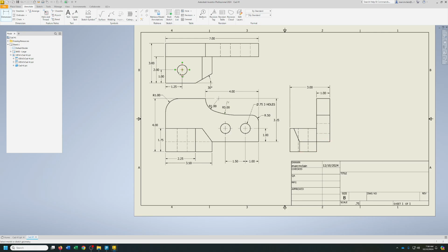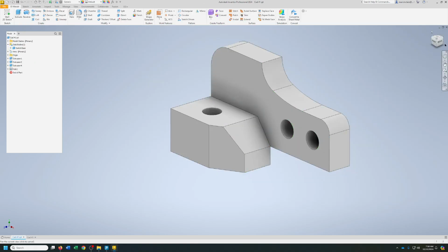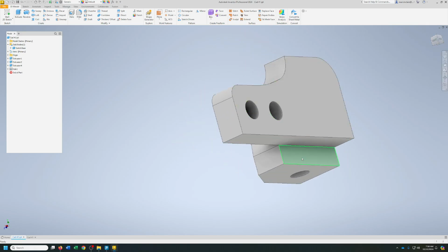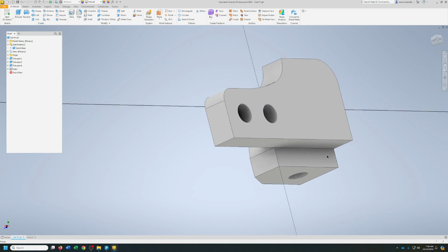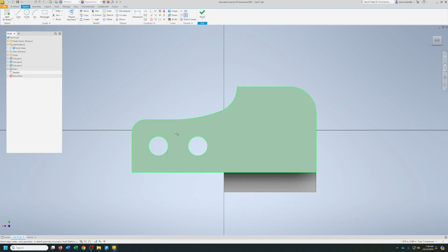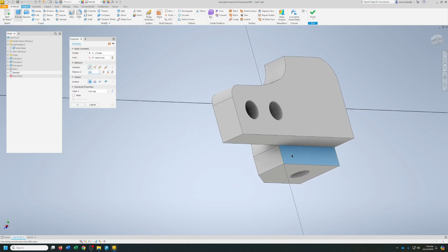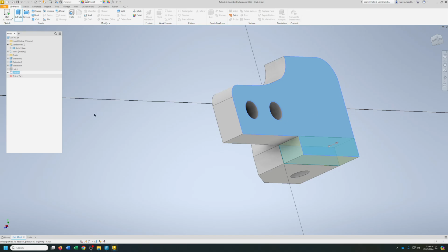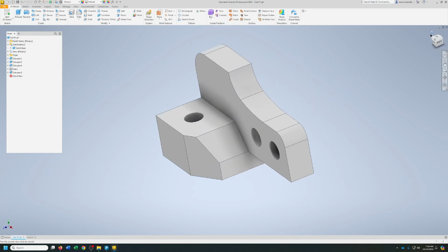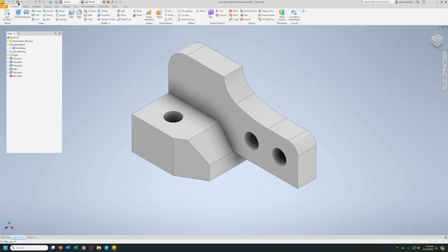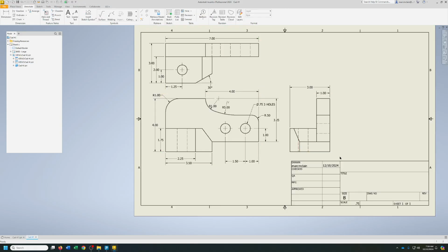Alright, see that? That needs to go all the way through. So what I'm going to do is I'm going to pick this, open, okay? Now, last thing to do, we're going to pick this, create sketch, project geometry, and I'm just going to pick that whole rectangle, okay? Now, 3D model, extrude, pick that to this face, and there we go. And then we'll resave that and go back to our thing and see it's updated here as well.